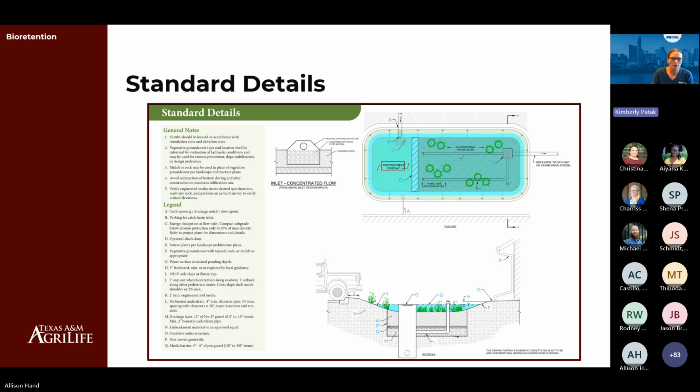Just similar to a wet pond, you want to trap those sediments and the larger debris in the pre-treatment forebay area. And then from there, you can start working on the main pool area. Typically, that pre-treatment volume is 20% of the water quality volume, just like in the design of a wet pond.